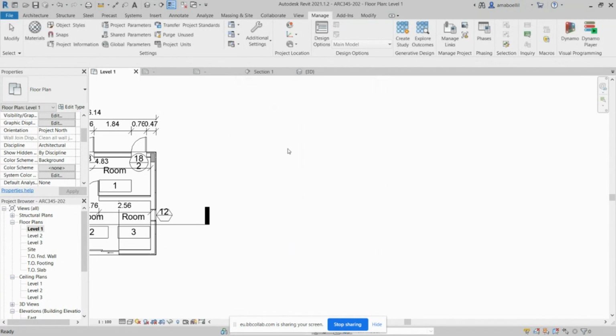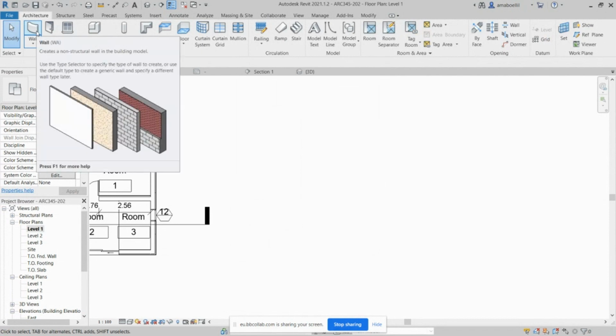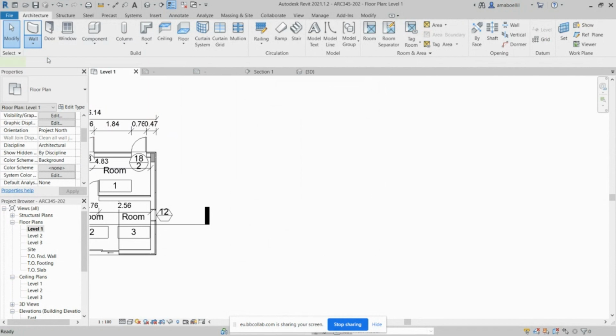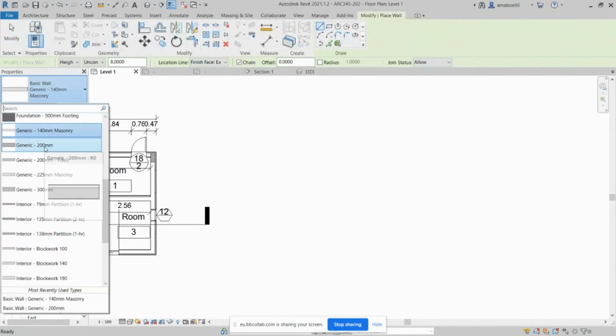If you hit the OK button, what you do next is that you go to the architecture and then start to tailor your wall. What kind of wall you want to have? We said we have 2 options. Once we pick the architecture, if the wall is a non-load bearing wall, we can pick generic and go with it. It's just generic, something that is just 2 lines, and then we can adjust it afterwards.